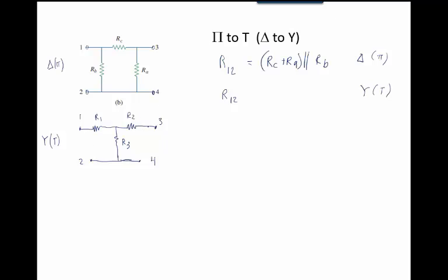So this is a resistor sticking out in the air as far as I'm concerned. It's just hanging, sticking up out of my proto board, this resistor right here. So it doesn't affect the circuit at all. If I measure my resistance between here and here, I will see R1 plus R3. This is not affecting my circuit at all, because there's no loop here. It doesn't complete any circuit. Even if you use your multimeter, you have to complete a circuit. So if I have my ohm meter in here trying to complete the circuit, I have a complete circuit to measure ohms.